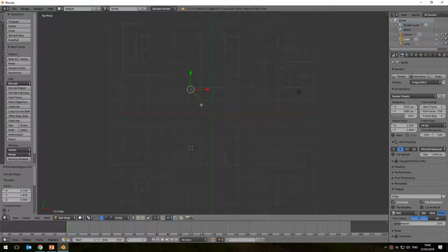So once I click, I've now created that line. But I'm going to press E for extrude again, and you'll see that now from that second dot, a third dot appears, and again I can move my mouse around and click wherever I want. Press E again and click. E, move, click. E, move, click. And you'll see that by pressing E and then moving and then clicking, we can create what appears to be something like a bow tie here at the moment, but we can create our object. And then I'm going to finish on the same dot as I started, like that, and there we are.